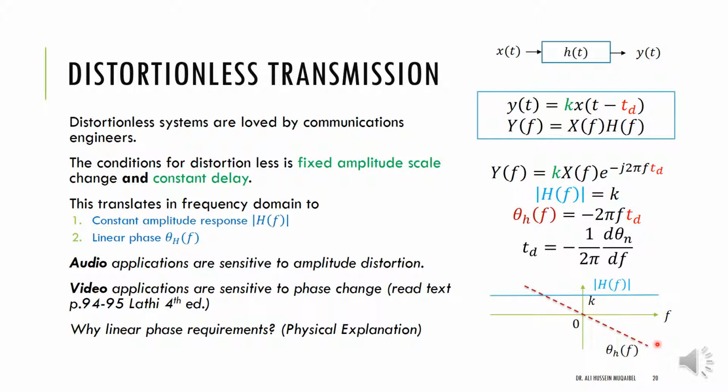This is a note. Again, distortionless transmission requires constant amplitude and constant delay, or in frequency, constant amplitude and linear phase, and not constant phase. Recall that audio applications are sensitive to amplitude distortion. However, video applications are more sensitive to phase change.